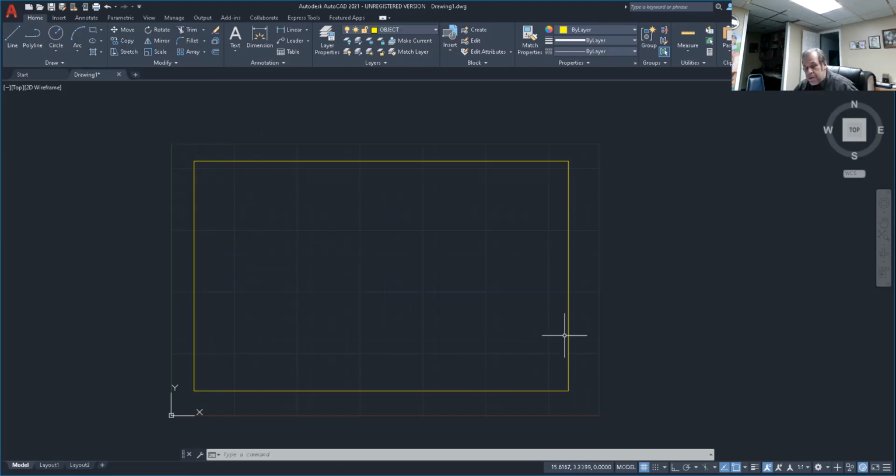Now, we want to start out by drawing our 3 principal measurements: height, width, and depth. So if you look at that drawing, the height is equal to 1.5. Okay, does that make sense? Our width is equal to 5. And our depth is equal to 2.5. Do you see those 3 measurements, height, width, and depth, on the drawing? Okay, so we're going to get our boxes first of all. Now in the front view, if you look at an object from the front, we're going to see the height and the width right here.